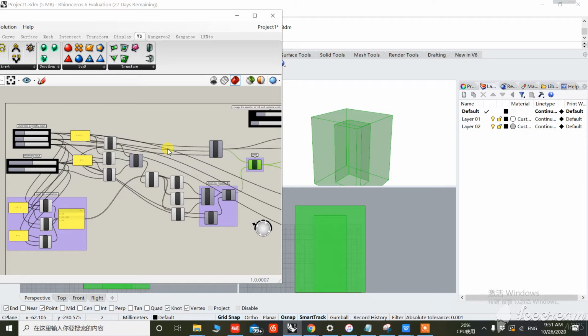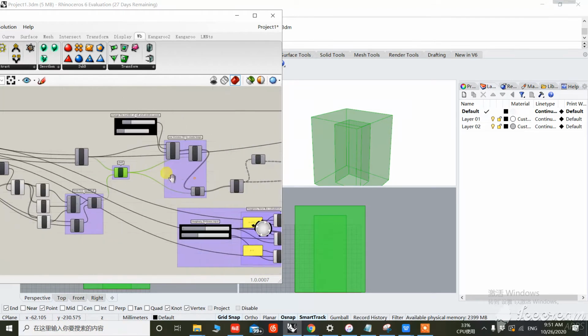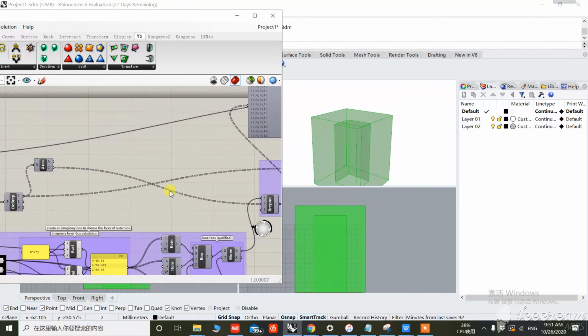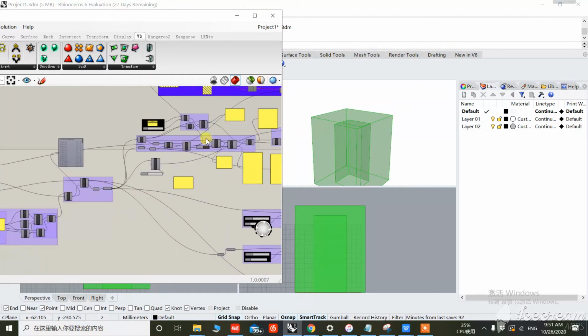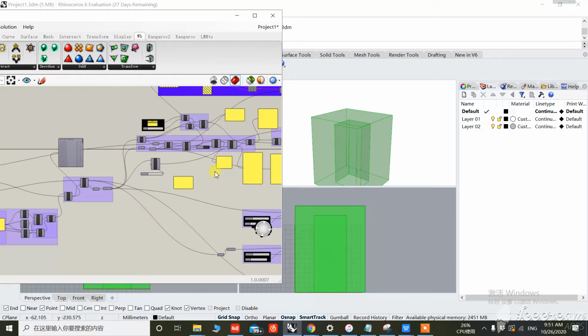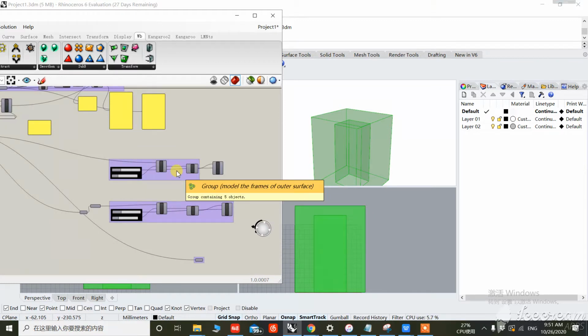Everyone, my project 1 is about the Beijing Water Cube. The main idea to get this parametric model starts from getting the shell, doing the Voronoi 3-dimension of the box and the intersection, modeling the bubble ETFE facade of all the faces with Weaverbird, and finally doing the parametric modeling of frame thickness with Weaverbird.